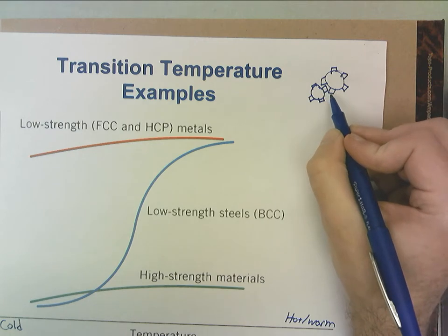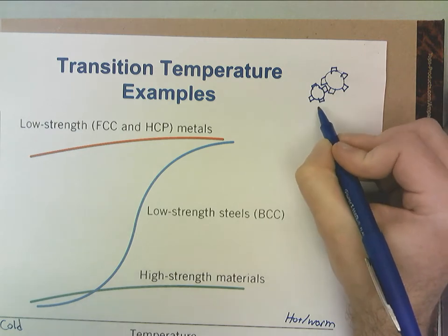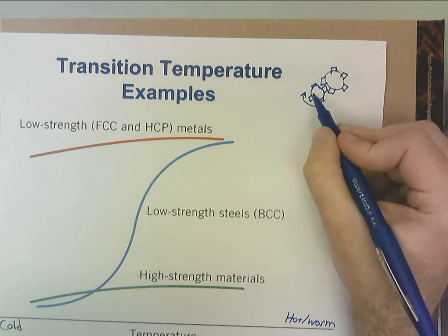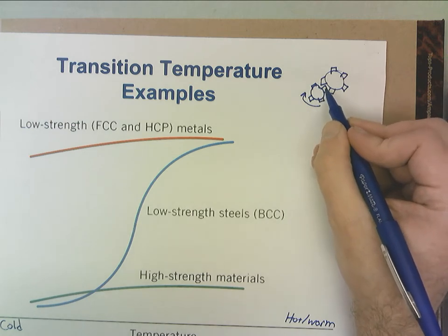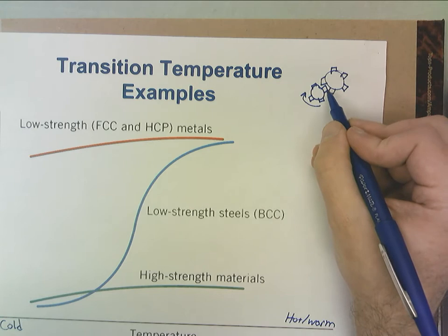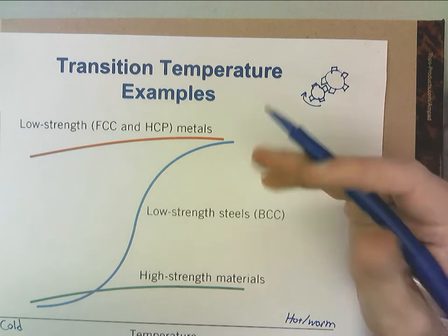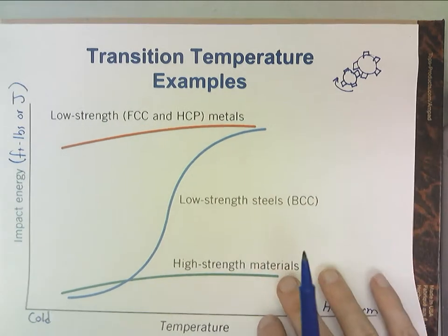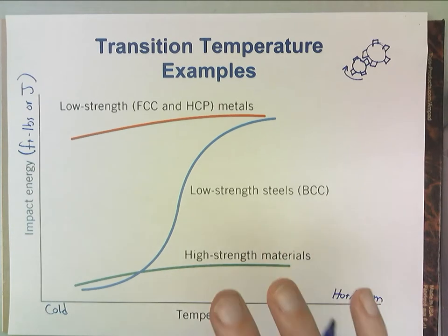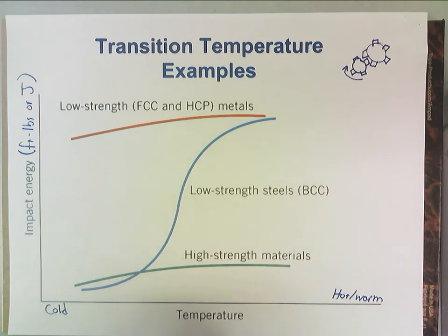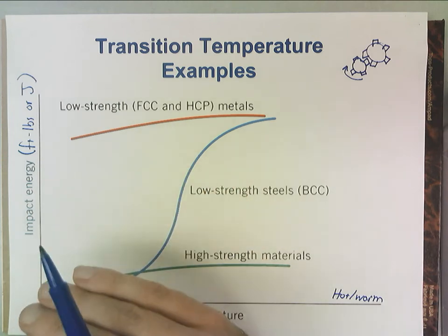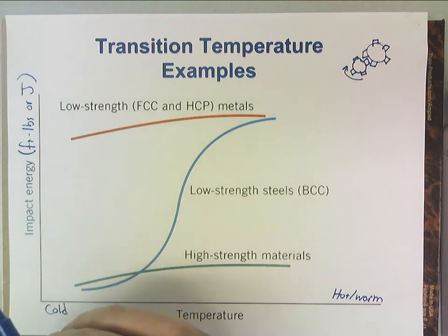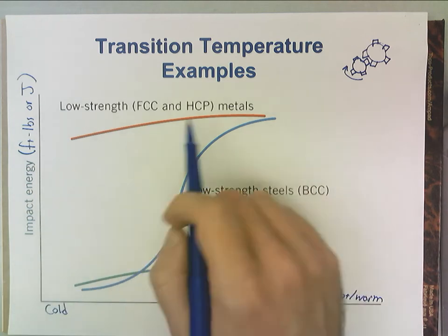Starting and stopping these gears suddenly, let's say we suddenly apply a torque on this gear and this gear is passive, it's receiving the torque. These teeth are impacting against each other. If this material doesn't have a high enough impact toughness, the teeth just shatter off in a brittle fashion. Just one example, any stop and start sequence in a motor of any kind, a pump of any kind, planes, trains, and automobiles, all of that stuff, you're going to want impact toughness.